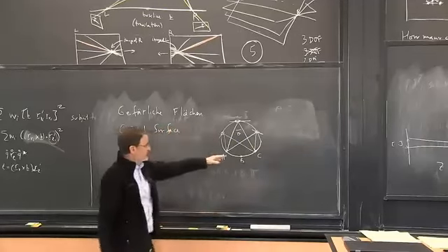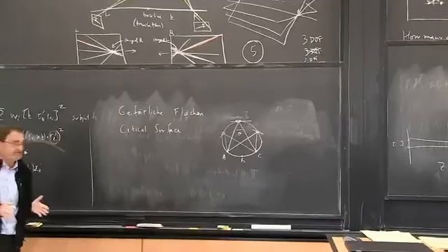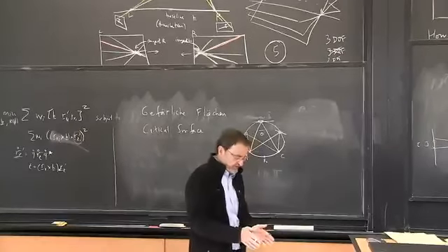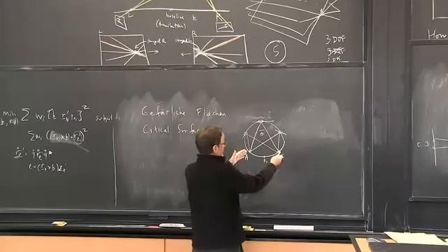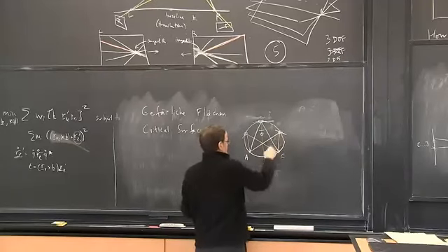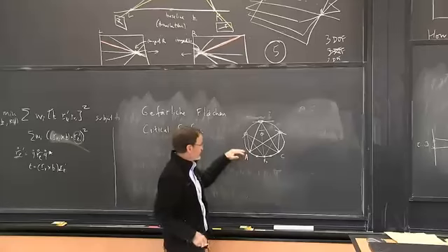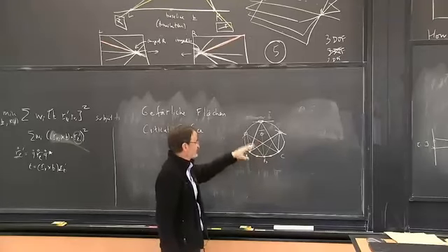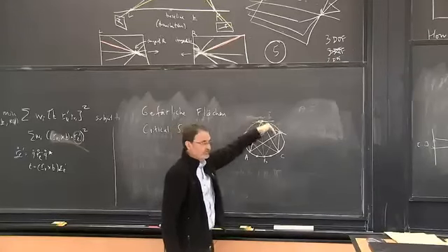Right, so what am I measuring in the image? I can only measure angle. I don't know distances. So if I move and the angles don't change, then I have a problem. And I've done it for A and C, but obviously the same is true for A and B, and any other number of ground points you want to add. So in this situation where you're flying right above the axis of a semicircular valley, it's going to be impossible to distinguish different positions along here.